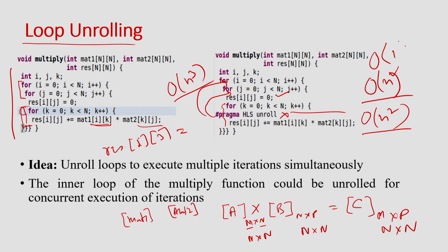So, then you have kind of constant time to execute this. But obviously, this performance improvement comes with a cost, right. So, here, if you need a single multiplier, here you need order of n multipliers; if you put this in here, it is order of n square multipliers, and if you put this in the topmost level, it needs order of n cube multipliers, right. So, in the sense that you need to make a balance between these two, right.